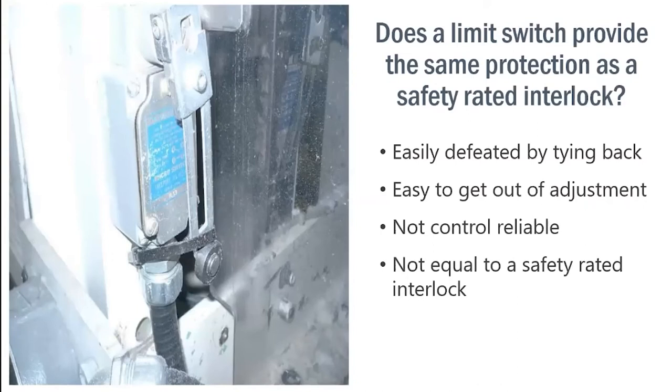They're not very robust, so they can get out of adjustment. They're not control reliable. And they're just not equal to a safety rated interlock. So you really need to consider, yes, this machine is 35 years old and came with a simple roller proximity switch, but does that provide the adequate level of protection you need for the hazard?